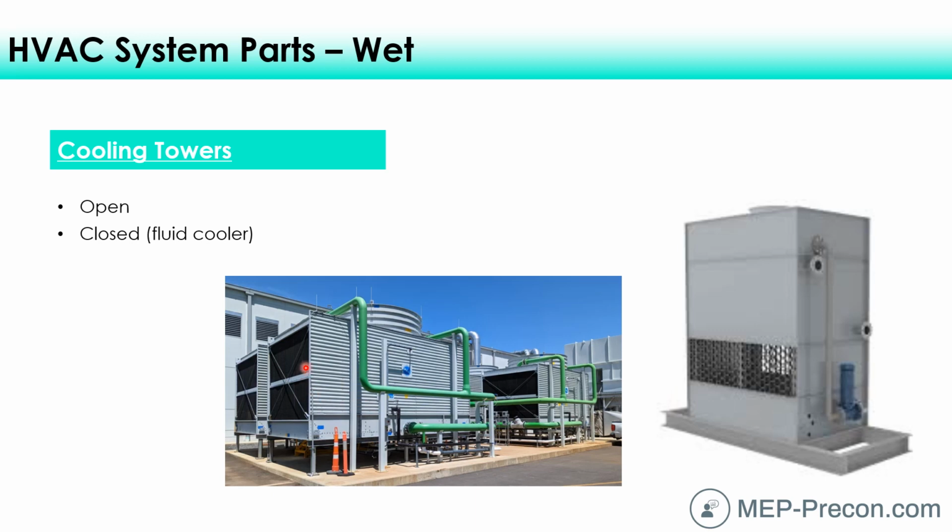You have a separate whole condenser water system, but the energy savings on this is a lot better than an air-cooled system. And so if it's a large capacity building, a lot of tonnage, then it would probably pay off if you're going to have it for a long period of time. Those are some of the things that an HVAC engineer thinks about when they consider the system and talk to the owner as to how they're going to use it, if they're going to operate it for a long time, if they're going to maintain it themselves, and so forth.